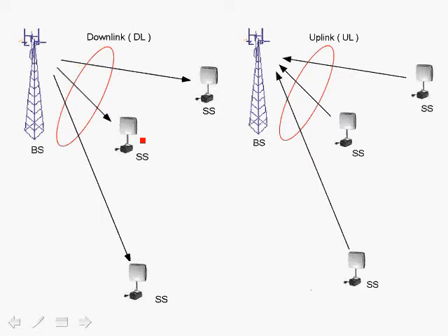After the downlink, the subscriber stations will know which subchannels and which slots are associated with them, which data regions, and they would commence with a transmission back to the base station with their data. There is a time gap between the transmission from the base station, the downlink to the subscriber stations, and when the subscriber stations turn around and transmit information back to the base station.